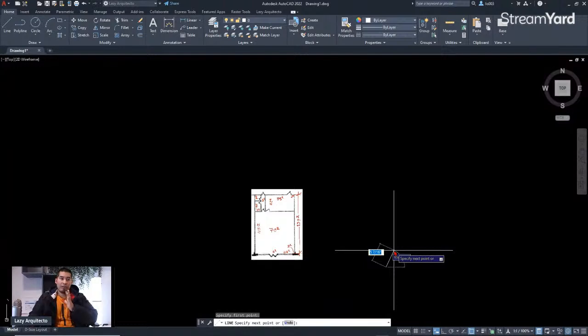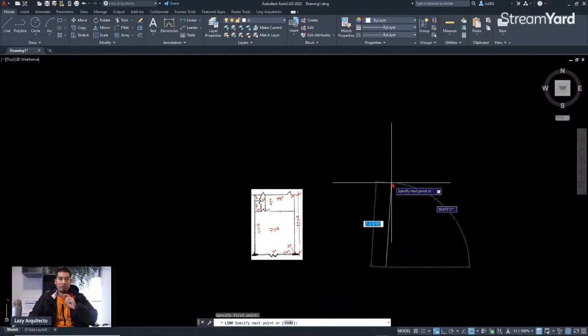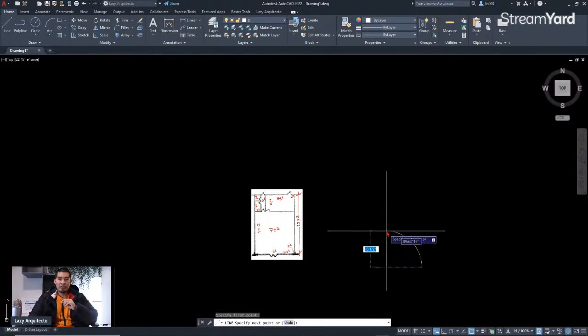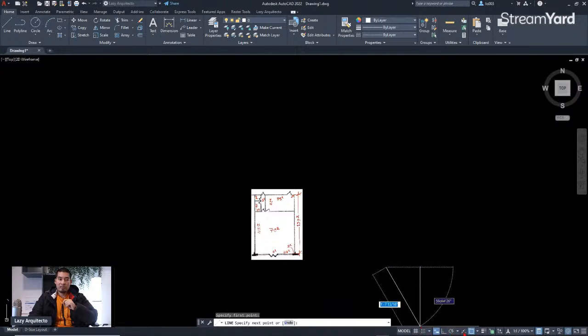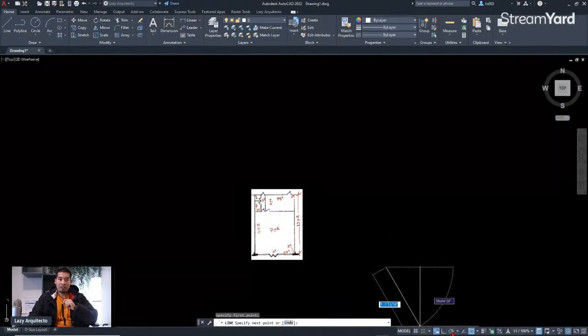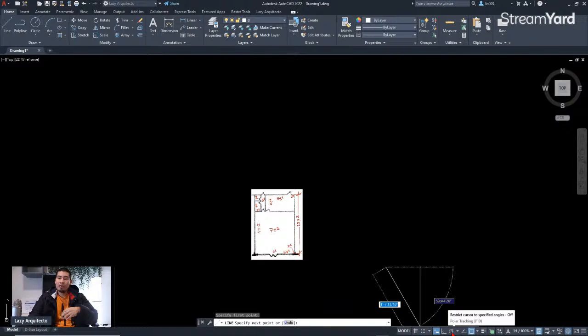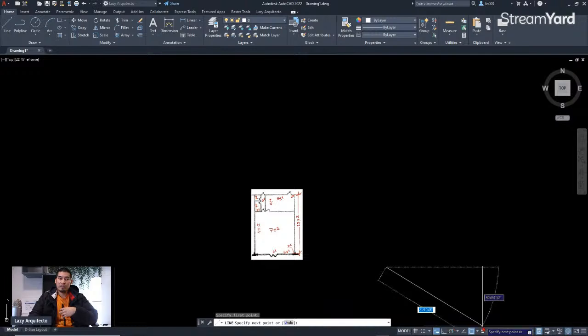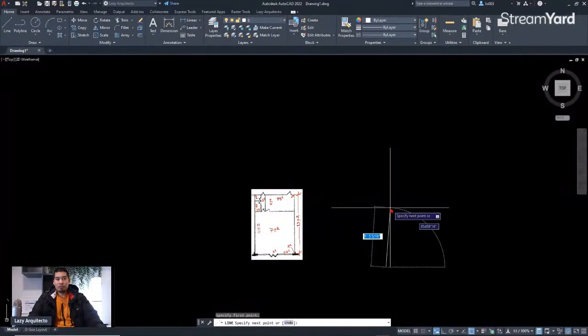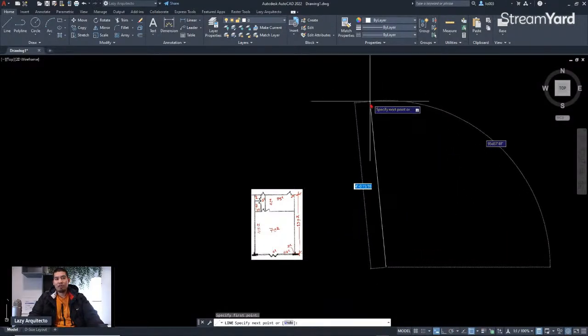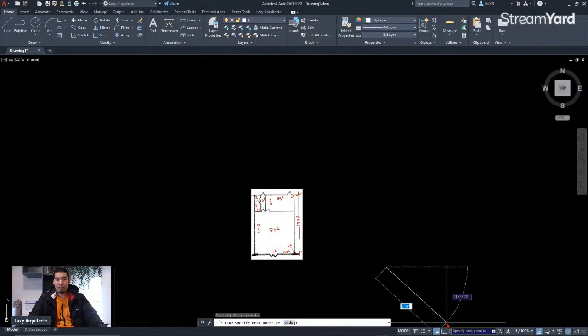So you saw that I want to draw this line nicely and straight. AutoCAD gives us these options on the status bar to check and uncheck the precision settings that we need. So in order to draw, for instance, my line straight, I need to activate this option on the status bar, which is the ortho mode.